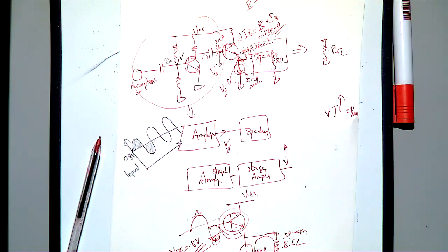But then you are having some problem, some region you are still missing. See, that is Q1 and Q2 of some region. So why, in that region of Q1 and Q2, are you not getting the amplification? Because here I have taken 0.8 volt, here I have taken again minus 0.8 volt. If you connect like this, your signal without any DC bias, what will happen? Without DC bias, if you connect like this, below 0.8 volt, both the transistors will be off. You know what I meant?